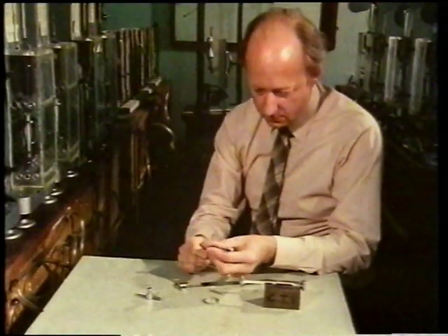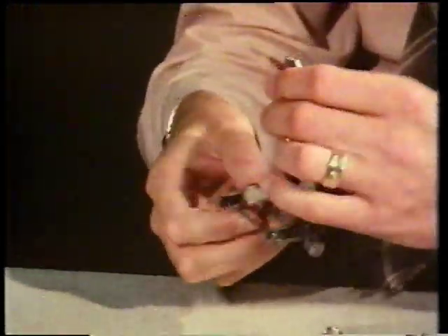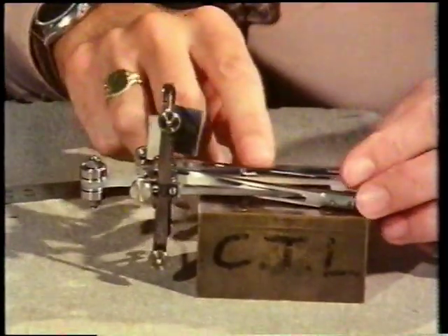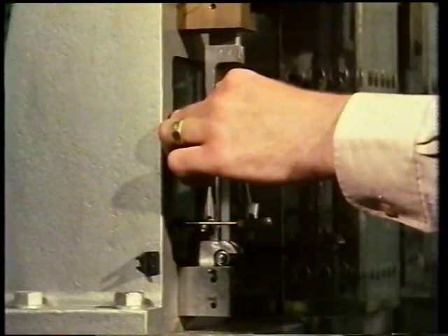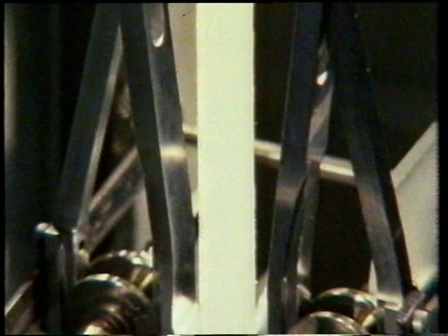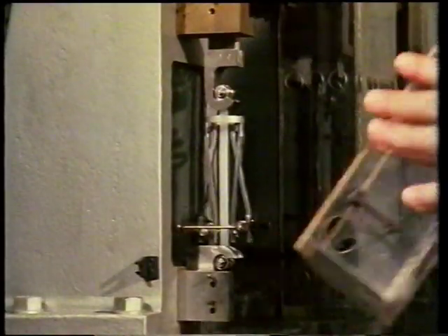The extensometer is an optical one. It works by mirrors rotating the reflection of a light spot as the specimen extends. The specimen is placed in the grips of the creep machine. There are the lower knife edges of the extensometer, and there are the upper ones. It's the relative movement between each pair of lower and upper knife edges which rotates the mirror.